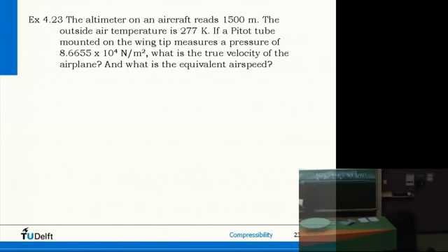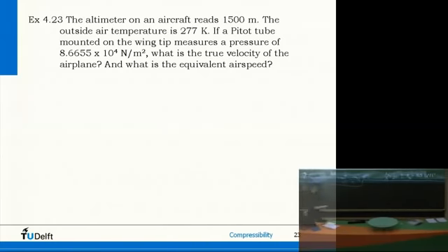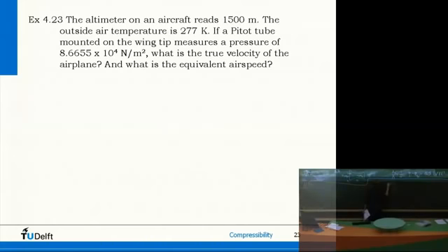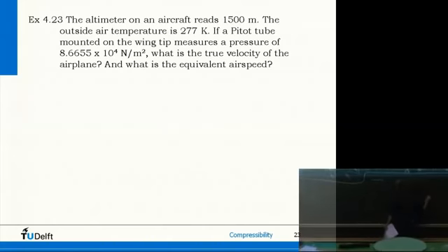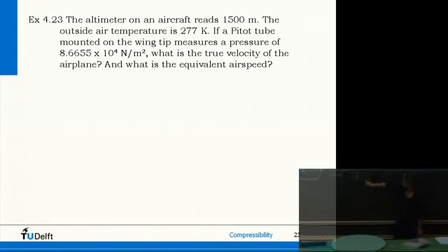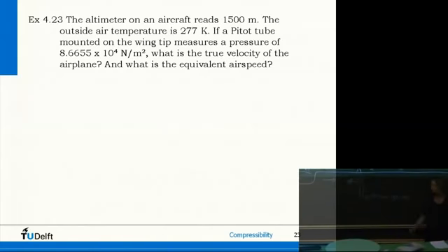So first the pitot tube. That's a way to measure. We had the manometer measuring pressure differences. The pitot tube also measures pressures. The pitot tube is like this. You have the flow. This is actually a very small tube. Flow flows into the tube and you have here a pressure gauge, sort of reservoir, where the speed is collected. The speed goes in, and then the tube fills itself with air. So what is the pressure that you measure here? Stagnation pressure, indeed, because it fills itself and then it doesn't flow through. So if you put this tube into the flow, this pitot tube measures the stagnation pressure, or total pressure, there where the speed is 0.